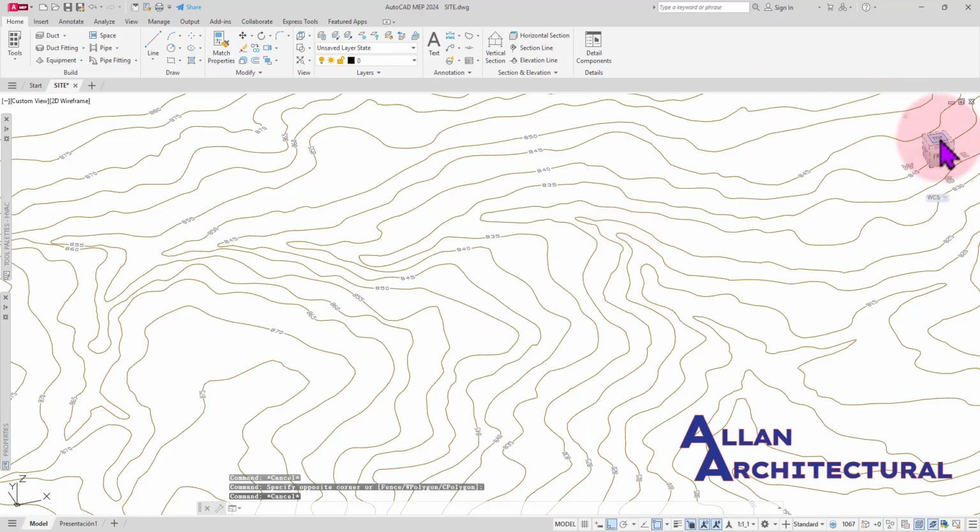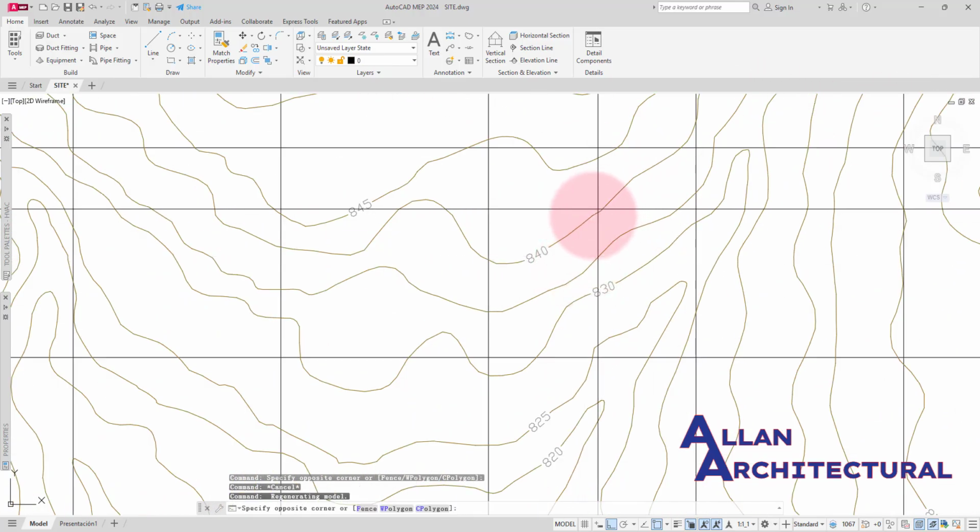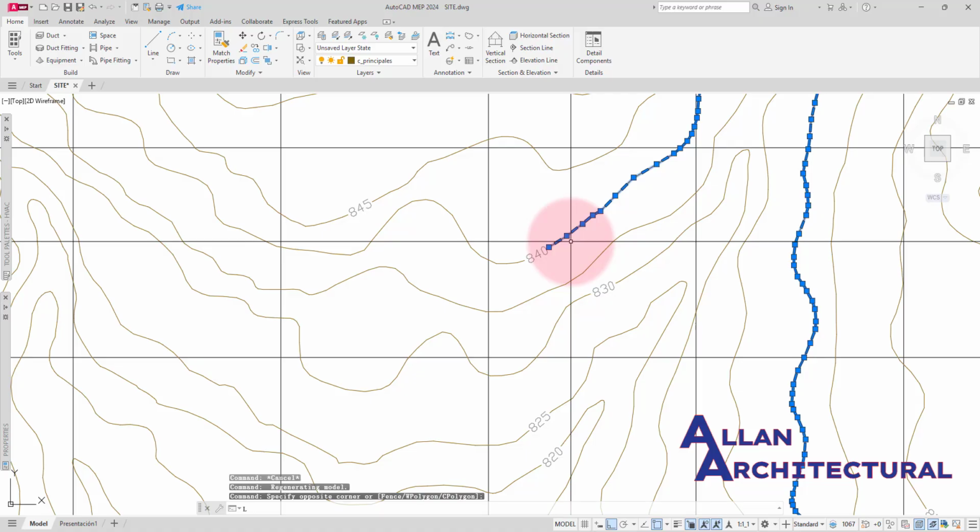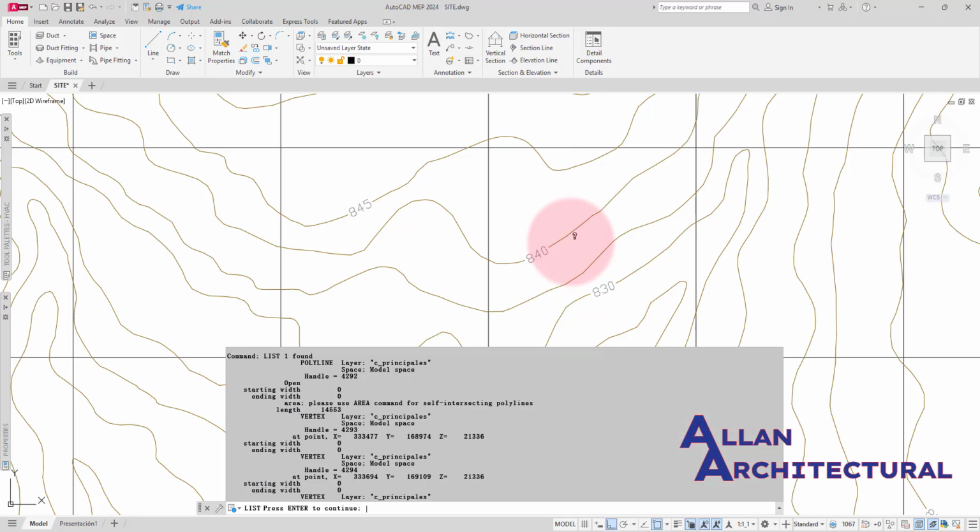All right, I think I know why. Let's just get back into the front, select this, and list that in there, and perfect. Now you notice in here we have the x coordinates, the y coordinates, and the z coordinates. All of these coordinates change when I select any of those different contour lines. The list command inside of AutoCAD is able to show me all of those projections.